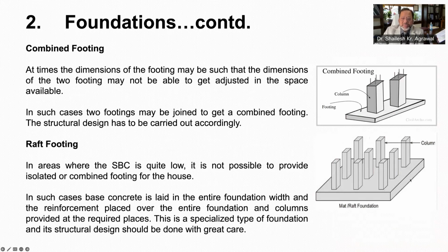In such cases, the entire area is excavated and first base concrete is laid over which reinforcement is provided for the entire foundation width, and then the raft is cast. This is a specialized type of foundation and shall have to be done with the help of structural design only.